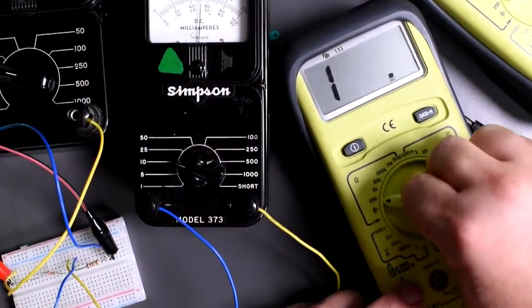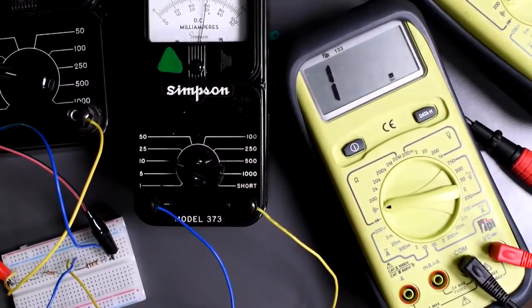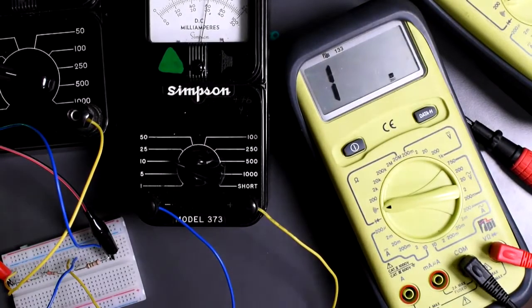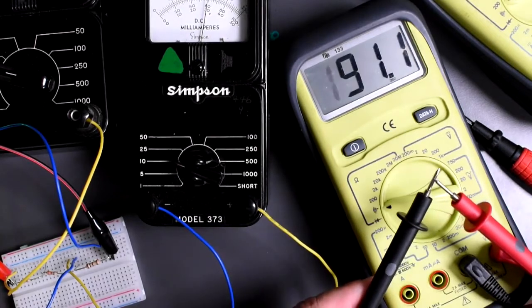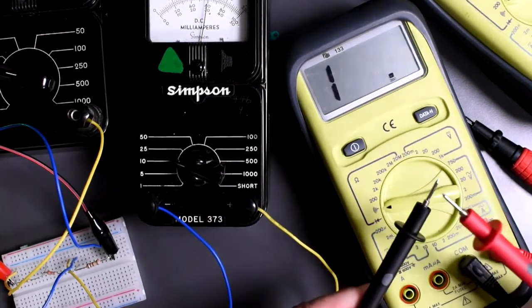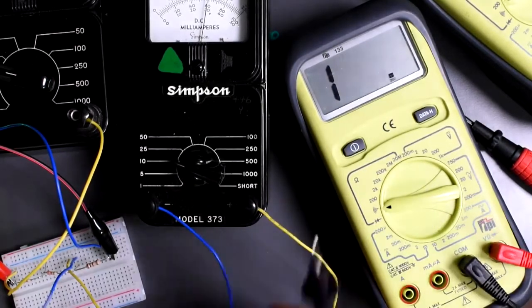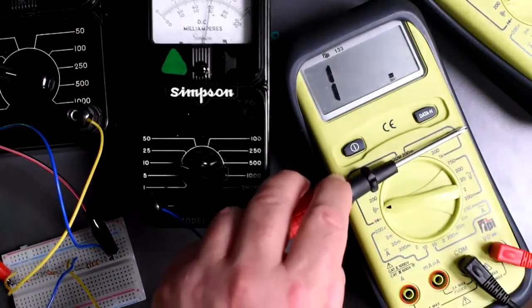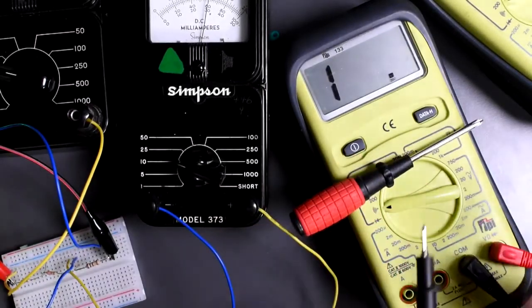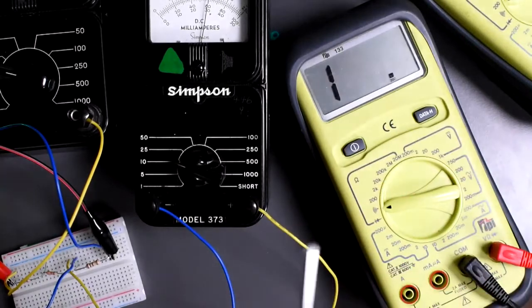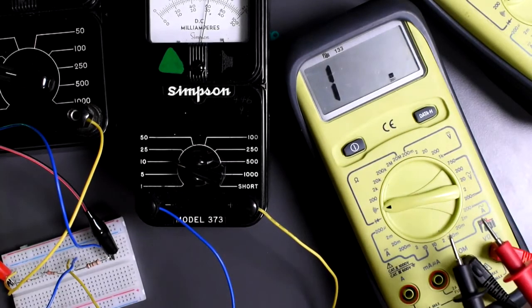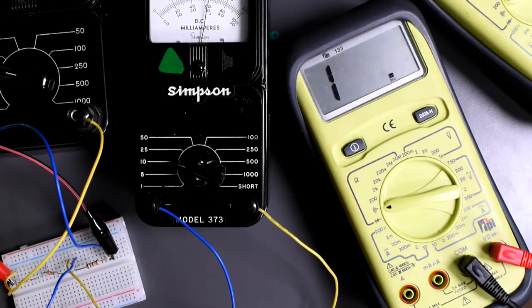We're going to select the continuity tester, and what we're going to see is a little bit of tangling happening here. These are the probes for this multimeter. If you make contact with those probes, you're going to hear a beep. Sometimes quite annoying, but this way it just tells you whether something is connected or not, if it's a clear path. So this screwdriver here is metal, so yes, there's continuity between that. If the cable or the wire was broken, it might show you no continuity, as it is right now. Right? So let's keep going.